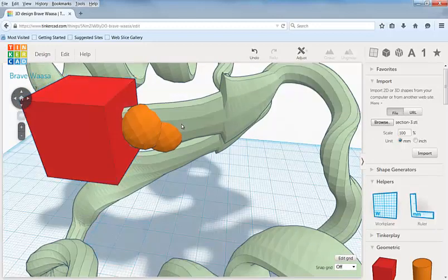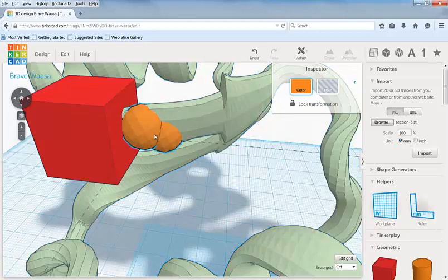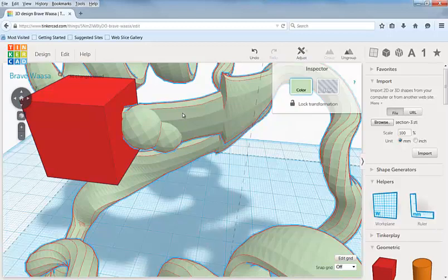One thing we're going to need to do at this stage is some merging, and we'll unmerge these when we're done. But for right now, I'm going to click on this piece, hold my Shift key down and click on this piece. I've got these colored different things, and I'm going to just group that. I have to wait for this to finish up because it's merging those two pieces together.